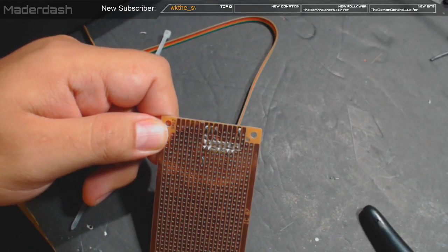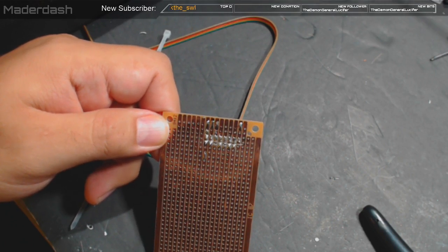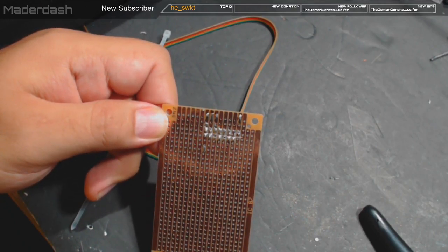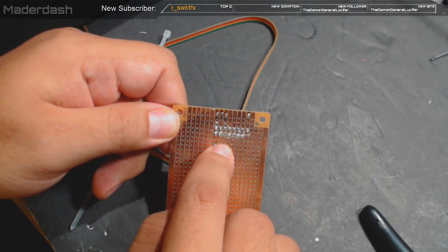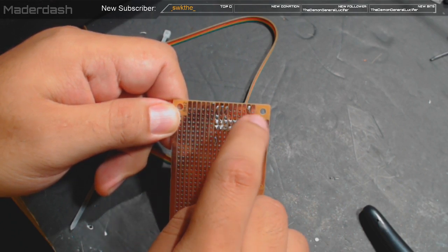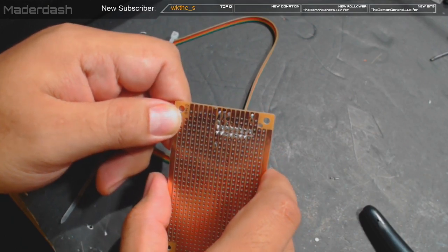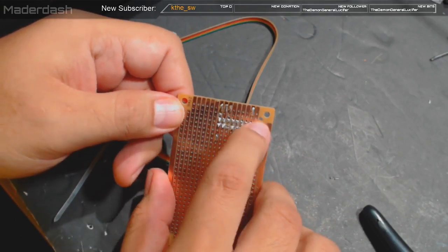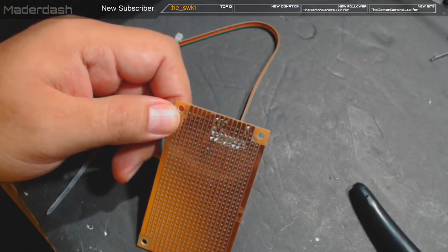or even like a 1/8 watt resistor, or a 16th watt resistor, or something right there that'll burn up, just as a precaution in the future. So that's why I went ahead and skipped 1, 2, 3, 1, 2, 3 on each one of these legs. That way, if I need to insert something in there for safety reasons, I can. I made the board a little bit bigger than what it needs to be. I thought, well, better safe than sorry.